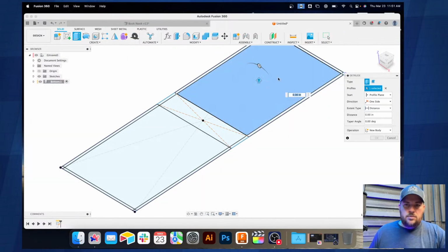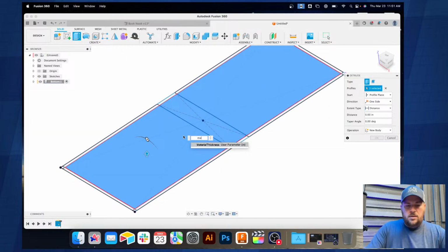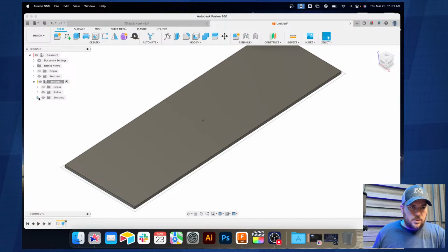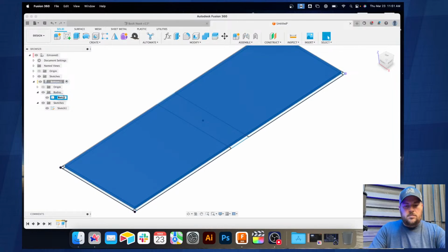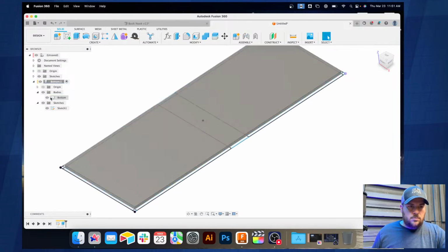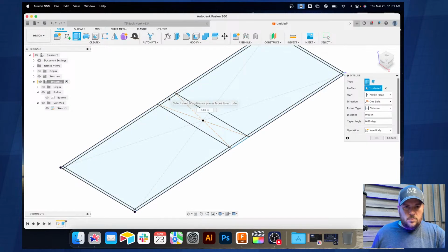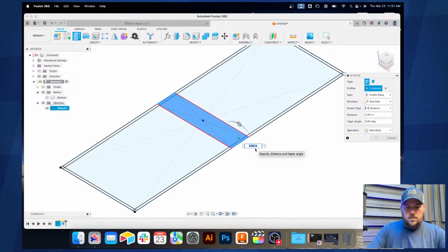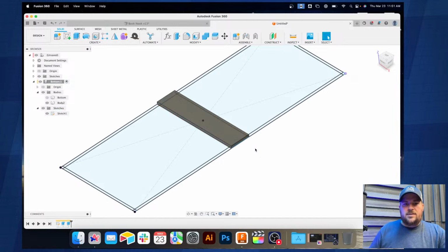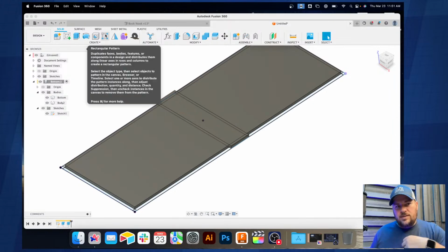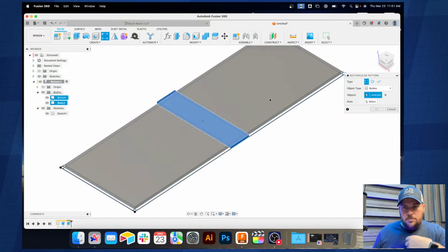I'm going to extrude the centerpiece up the material thickness, because again, I just wanted this whole thing done on the laser. I'm going to turn that sketch back on. And then I'm going to extrude, no, that one, and that one. And again, the only reason that I'm doing this is because I want that to eventually interact with all these pieces, but it's easier to do the rectangular pattern like I'm going to show you here when it's a body, because then you can adjust it.